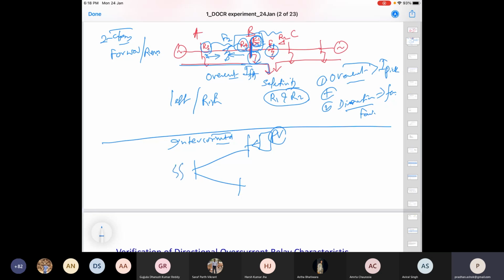So if this is the substation, a transformer here, the equivalent Thevenin's comes here. For a fault here, the path of current will be this, and also now with the presence of PV, this will be this. Earlier, the system without PV, or at night time when PV will not be there, was a radial power flow. Now power flow may be both ways, so current will also be both ways. So both the sources must be isolated.